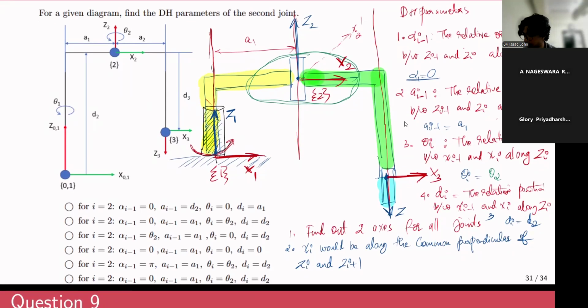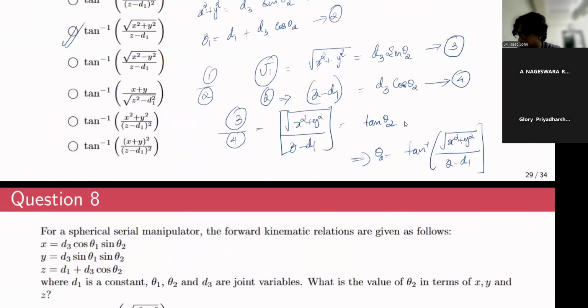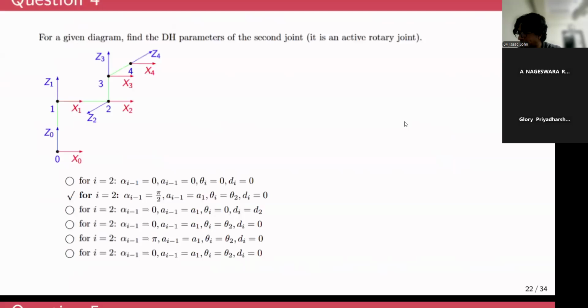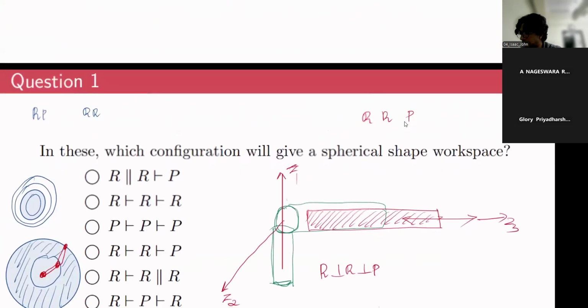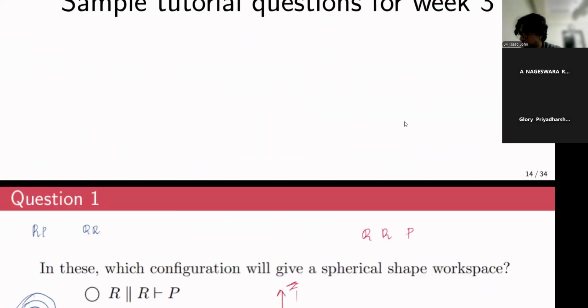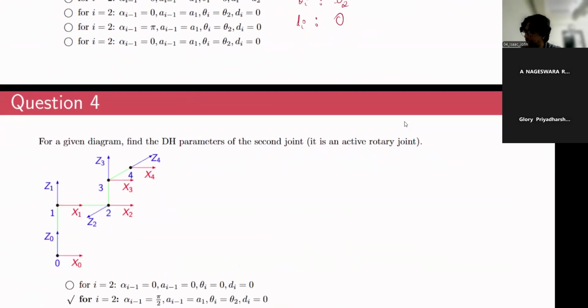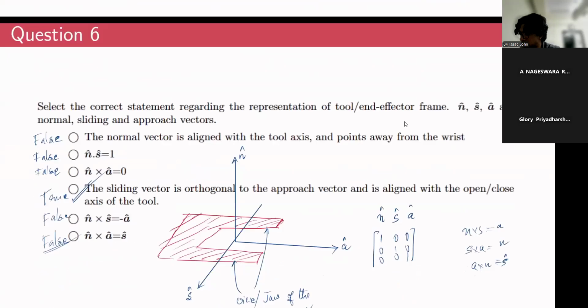Sir, next we have another joint, right, sir? This is a revolute joint. The other joint is a prismatic joint. Yes. So how will that joint work, sir? So in a revolute joint, you can only rotate two links about the axis of the revolute joint, but in a prismatic joint, two links will slide along the axis of the prismatic joint.